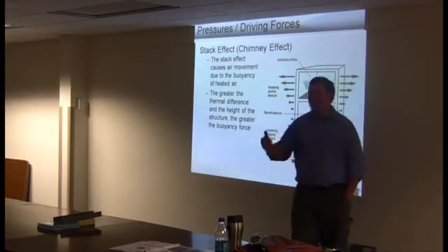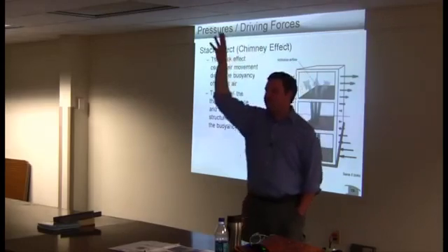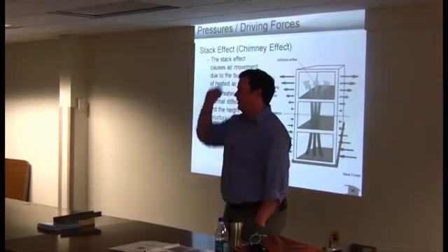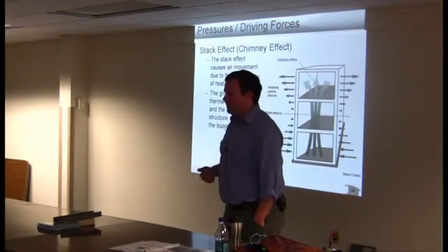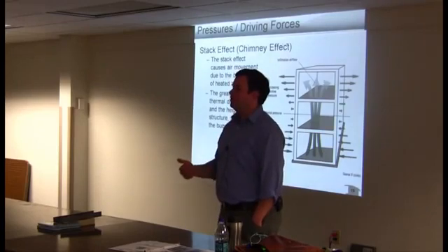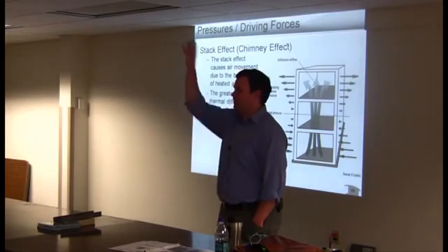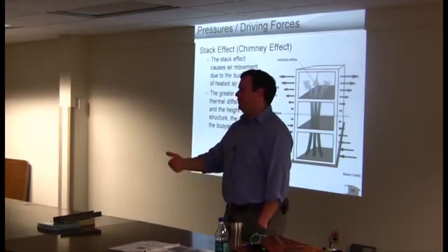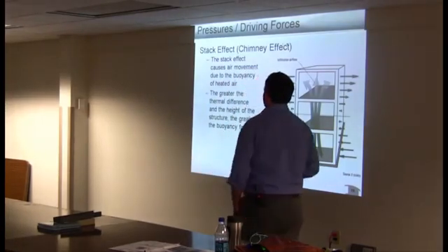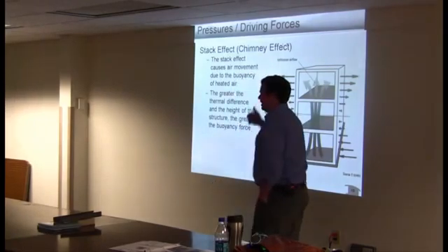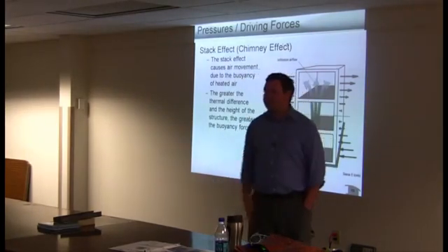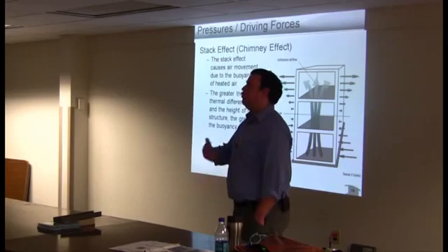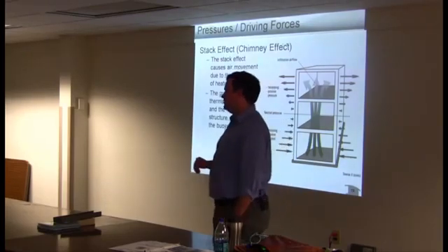And so you've got warm air pushing out at the top. That's creating a positive pressure zone, and it's also creating a low-pressure zone at the bottom. So you have air wanting to push out at the top of the structure, and the building tries to make up for that with air being sucked in down at the bottom of the structure. The taller the building gets, the bigger the role stack effect is going to play in pressure differences within the building.